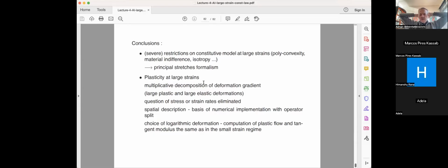And then by using this approach, I can split geometric nonlinear part and the computational plasticity. And then by using logarithmic strain measures, I recover something that looks very much like what I've done in the small deformation setting, only adapted to the principal direction. So once I have principal direction, I'm just doing the stuff that I was doing before. So that means that I can take each and every complicated plasticity model or damage model or coupled damage plasticity that we've done in a small deformation setting, you can plug into this type of framework.